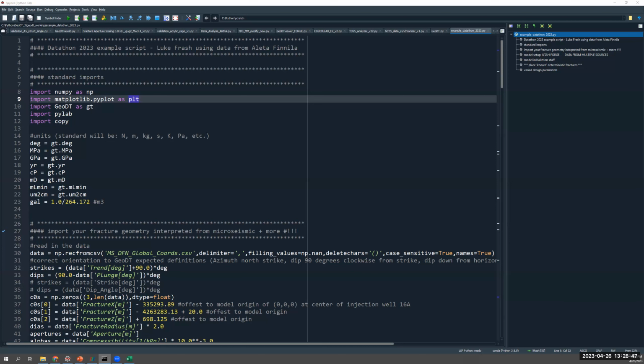But just generally speaking, the GeoDT solver will model the well as a flowing pipe, and then it will model what's called a choke as the connection between that pipe and the fracture. And then it will have another flow element that models the flow through the fracture itself. So it does have the ability to account for the complexity of high pressure losses in the near wellbore zone, but the perforation diameter, those kinds of variables are not yet implemented in the code.